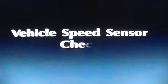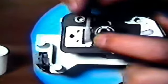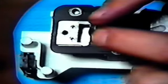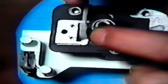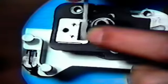Finally, we want to check the vehicle speed sensor. To maintain an accurate vehicle speed signal to the ECM, it's necessary to remove the speedometer head, clean the reflective blades with alcohol, then lubricate the speedometer cables. We recommend this procedure every 15,000 miles. Now, we're ready to put everything back together in preparation for the final road test. As we do this, we continue to look for any signs of possible malfunction.